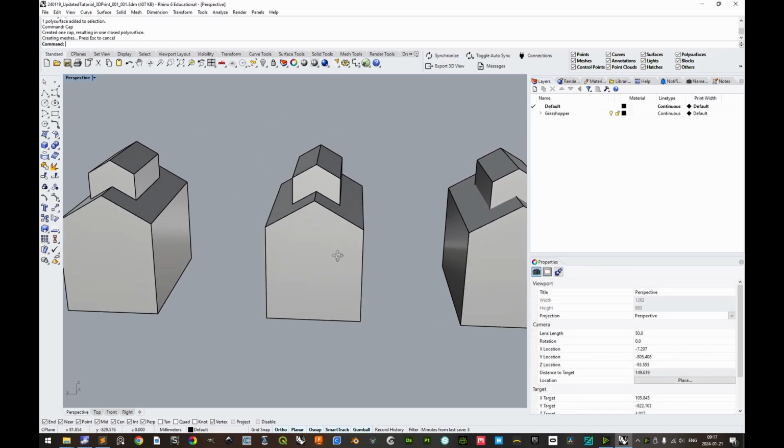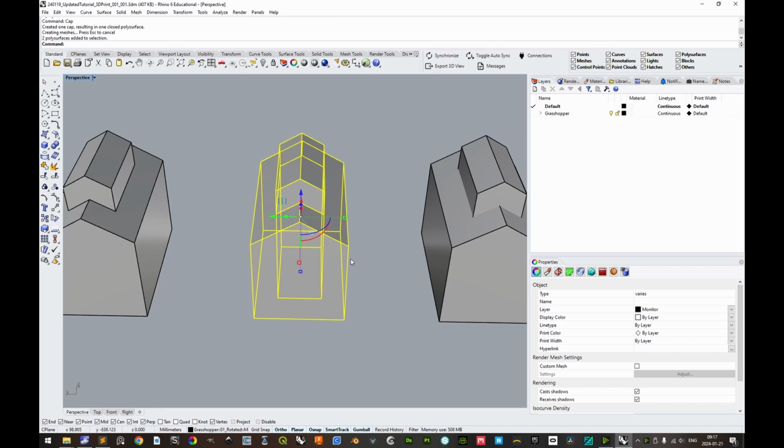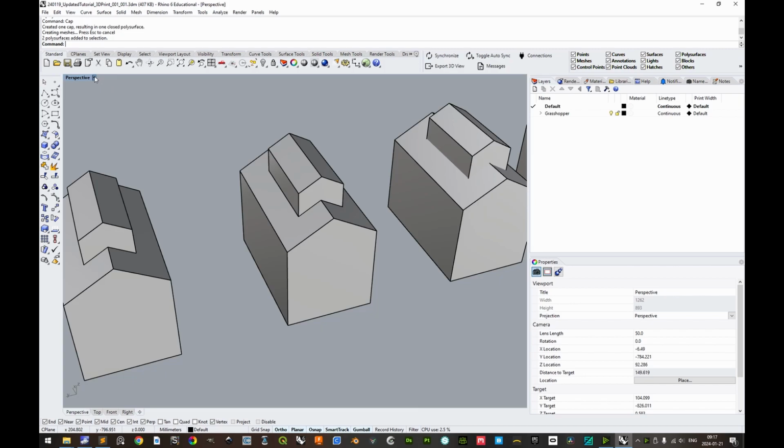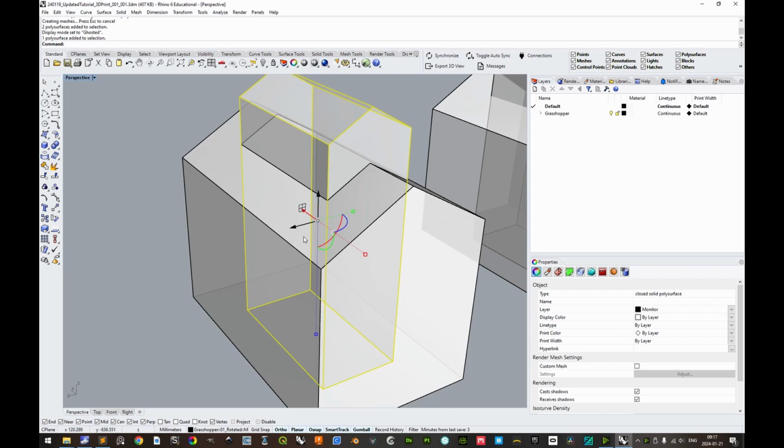For the second example, it is not a non-manifold object per se, but it showcases a trouble with non-manifold surfaces. If we activate the ghosted view mode here, we see that this vertical surface extends below the meeting with the oblique surface, which makes the portion below non-manifold, since this portion of the surface has 2 insides, both sides being inside of the surrounding volume.